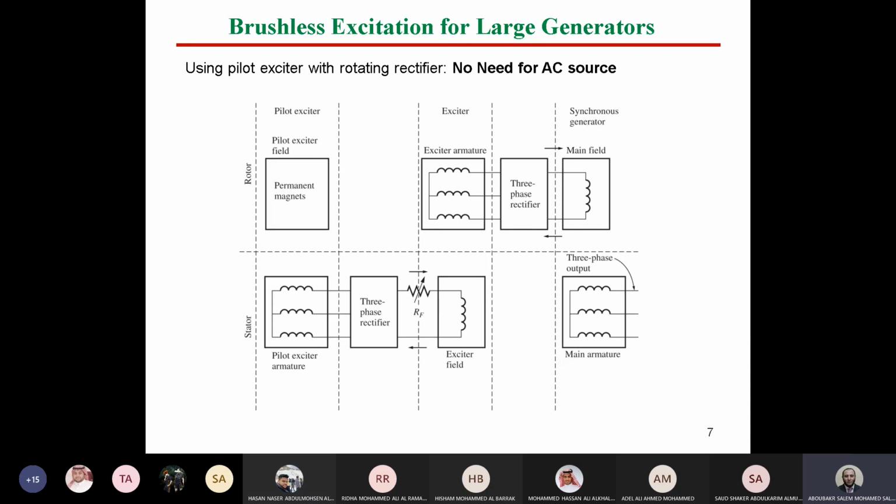Yes. Okay, good. Then we convert this AC to DC to supply another machine, which is the exciter. This is the stator now, okay? And this stator will produce flux, okay? And this flux will cut the machine winding here. So we will have also another EMF here. Is it right? Yes. This EMF can be converted from AC to DC by means of a rectifier. So we now could connect a DC supply to this part. صح كده? Is it clear?